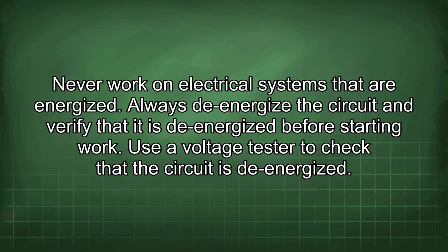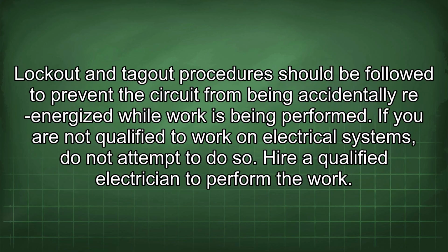Never work on electrical systems that are energized. Always de-energize the circuit and verify that it is de-energized before starting work. Use a voltage tester to check that the circuit is de-energized. Lockout and tagout procedures should be followed to prevent the circuit from being accidentally re-energized while work is being performed.